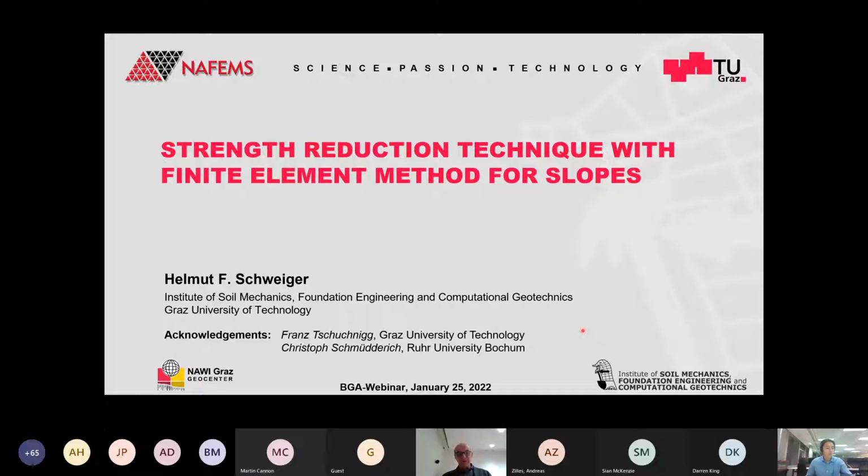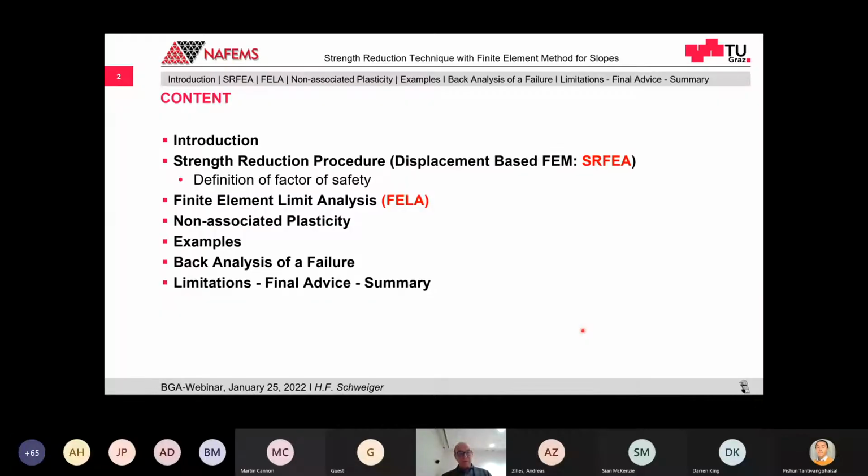So I will give you a short presentation on the strength reduction technique with the finite element method, in particular for slopes. And as mentioned before, this is a collaboration with the NAFEMS Geotechnical group I'm a member of. After a short introduction, I will try to describe the strength reduction procedure, and in some of the slides you will see the abbreviation SRFEA, which means strength reduction finite element analysis based on a displacement-based finite element method.